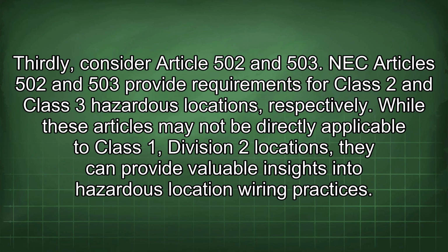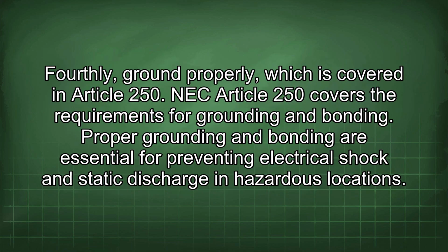Thirdly, consider Article 502 and 503. NEC Articles 502 and 503 provide requirements for Class 2 and Class 3 hazardous locations, respectively. While these articles may not be directly applicable to Class 1, Division 2 locations, they can provide valuable insights into hazardous location wiring practices.